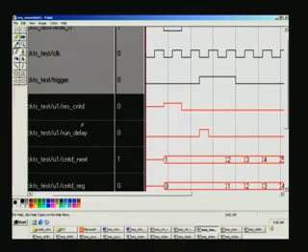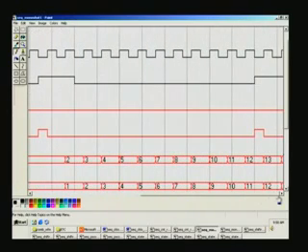And next we see here run delay is rising here, and here also somewhere when the counter is 12. The reason here is I purposely triggered it once again when the counter is already running, just to demonstrate this is non-retriggable. So it doesn't reset here, it merely ignores.